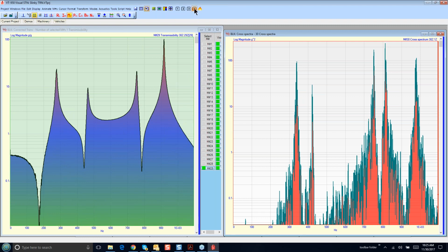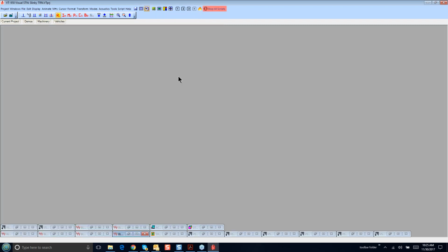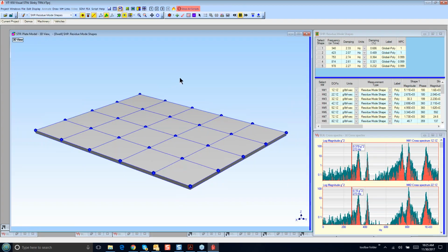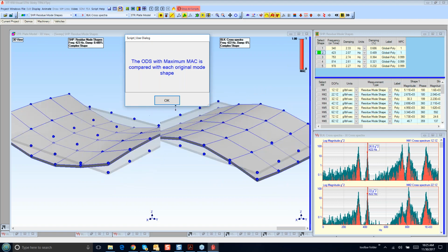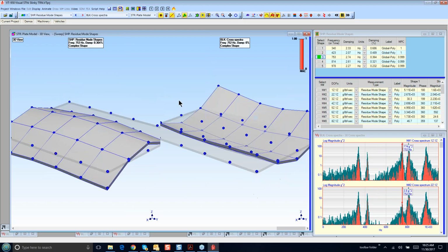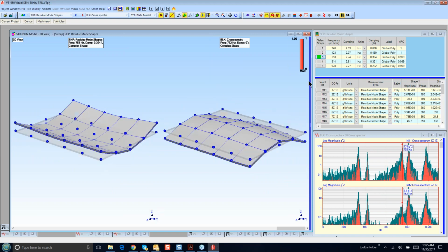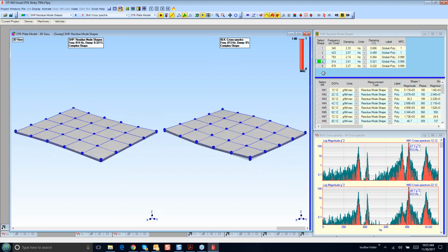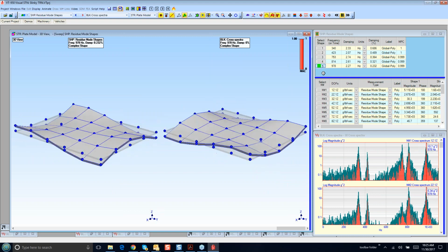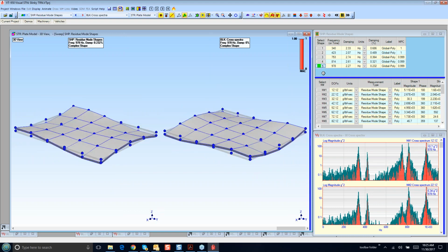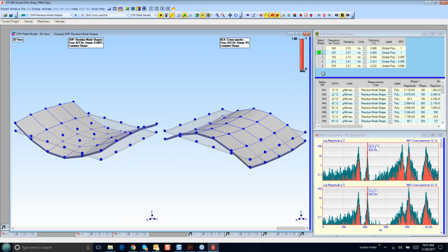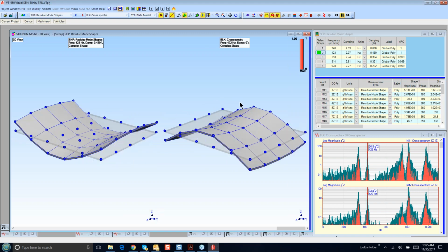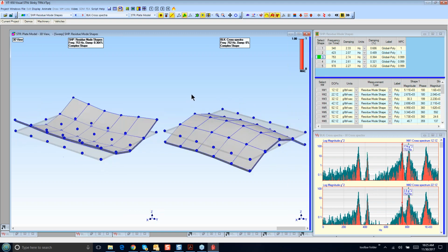And then the final one here is that we can do a comparison animation between the original mode shapes and the cursor position in the cross-spectrum data. So there's a lot of other details to talk about here, but you can see that we're sweeping through the mode shapes that were used to simulate the random response. That's our MIMO calculation, multiple input, multiple output, part of our advanced signal processing in MEscope. And you can see that we went a round trip here and recovered some ODSs.